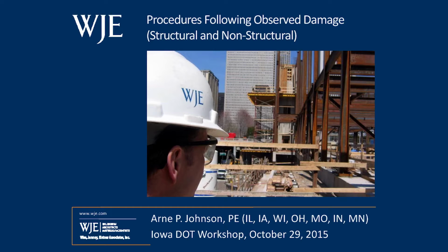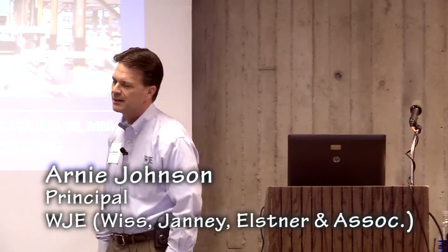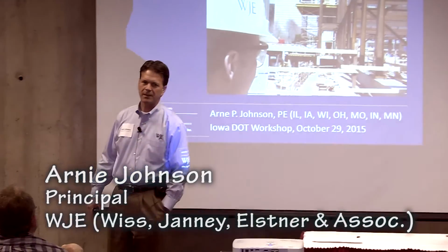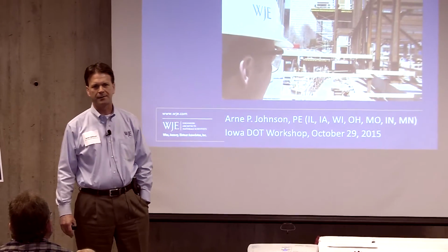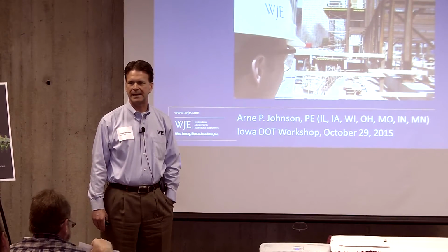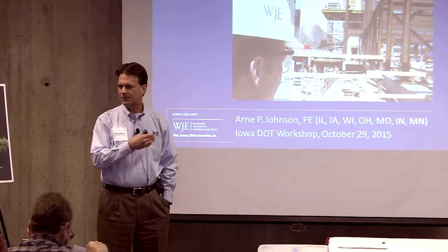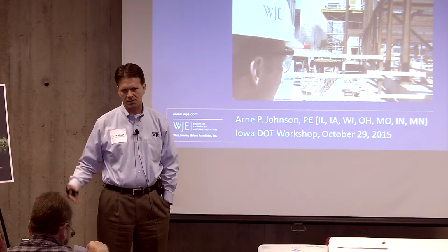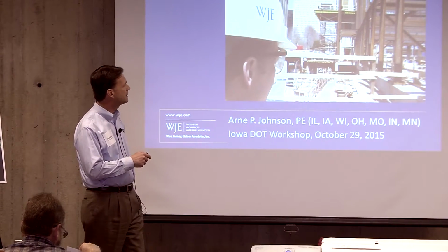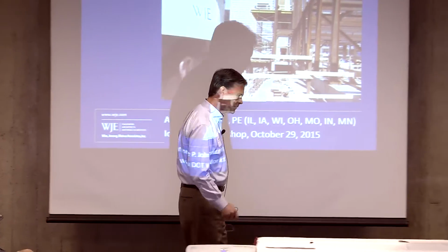Going to talk about structural damage. Now, I've changed the title to Procedures Following Observed Damage. And the reason I did that is because structural damage caused by vibrations is extremely, extremely rare. We keep our vibration limits so low that actually causing damage to a structure, as I referred to earlier, would usually take much higher vibrations. And so I'm going to talk about both structural and non-structural damage and what we do to evaluate it.